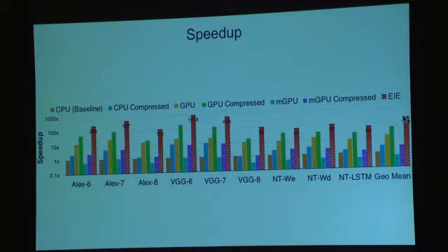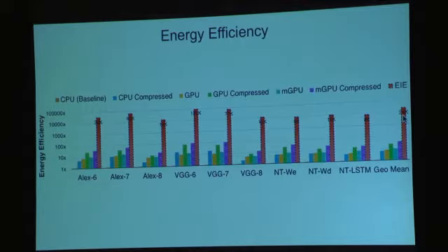About 180x. And that's because you're able to keep this entirely on chip. It's really a question of locality. Here we're keeping it not just entirely on chip, but all of the data is being fetched by SRAM sitting right next to the arithmetic unit, so it's down in that 5 picojoule bin. And for that reason, the energy efficiency is much larger. It's actually 24,000 times more energy efficient than the CPU.